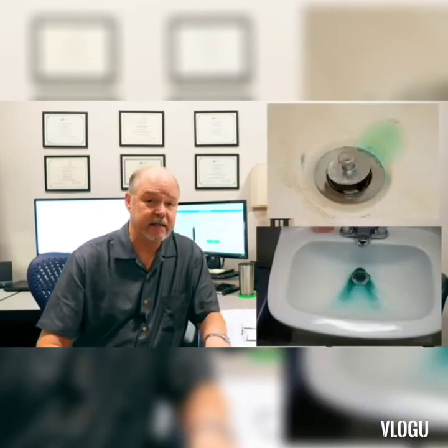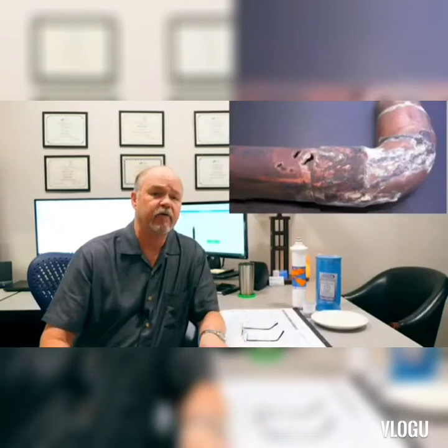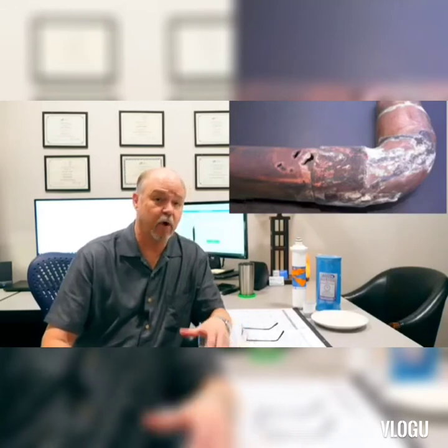By golly, if you have acidic water, you want to treat the whole house because that acid water is destroying all your plumbing. If you are seeing blue or greeny stains on your drains, that's what you've got going on. You've got acidic water that's actually eroding the copper from the inside of your plumbing. And if that's left unaddressed, what happens next is you'll get pinhole leaks. And you know Murphy's Law, those pinhole leaks are going to be behind a wall someplace and you're going to have lots of damage to repair. So acidic water is something not to be toyed around with. You definitely want to make sure that you take care of it.